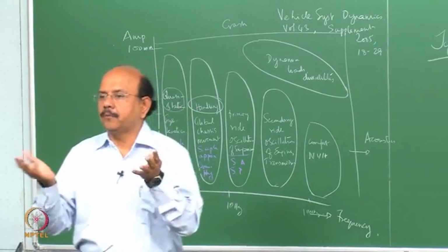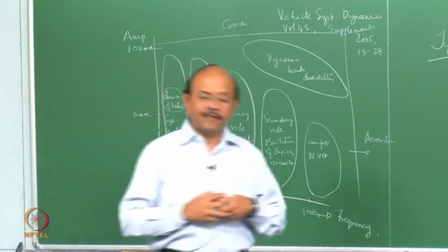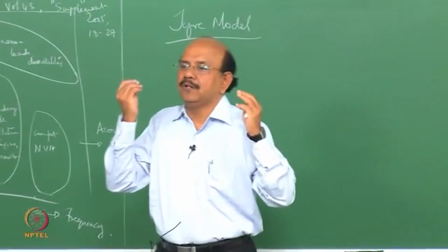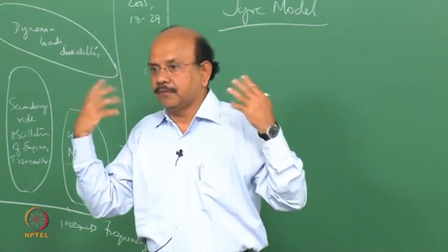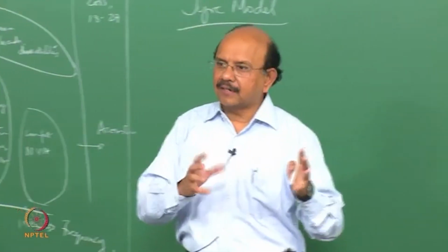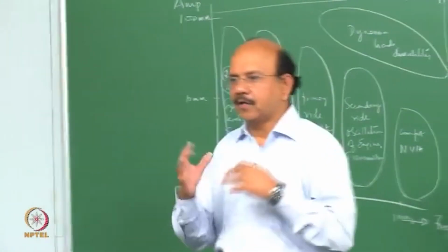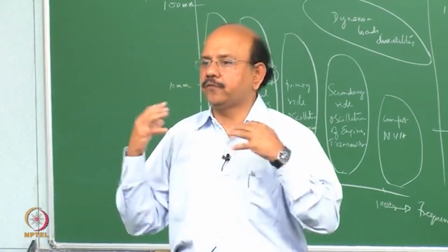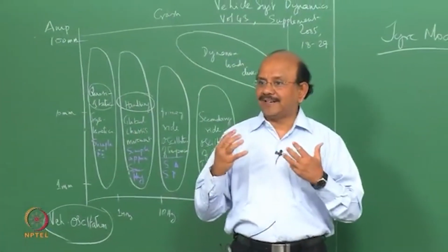Usually the range of hearing is from 20 to 20,000 hertz, and very interesting factors have come about. For example, your ear is very sensitive to frequencies of about 1,000 hertz. So the magnitude of noise, expressed in decibels, is now adjusted, and you have scales like the A scale which adjusts to the sensitivity of your ear.